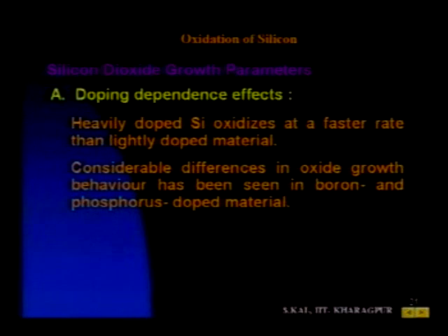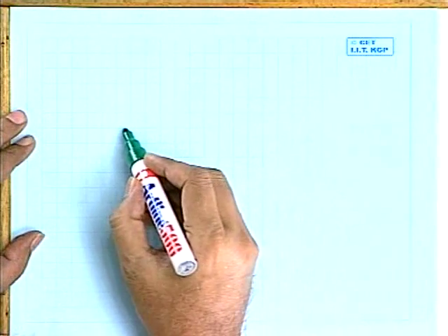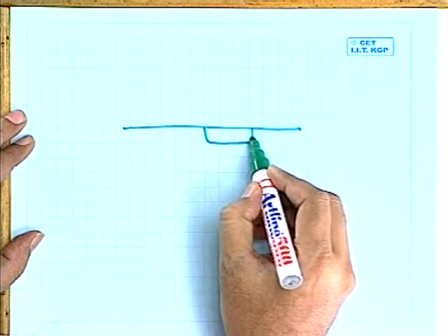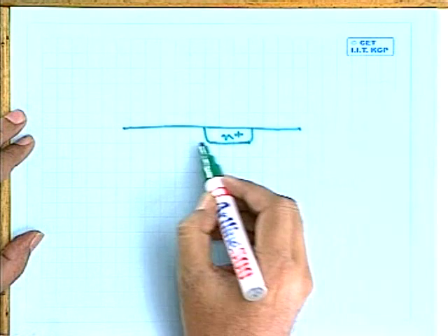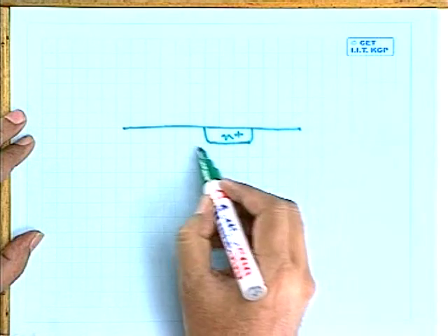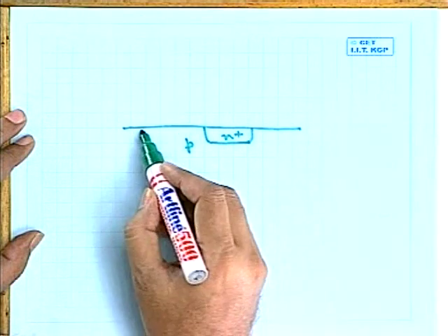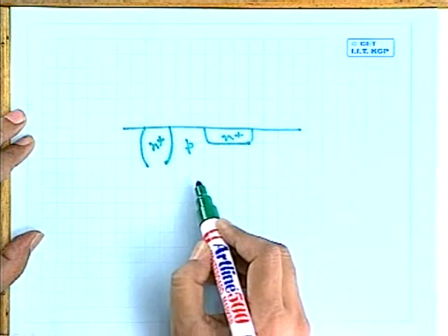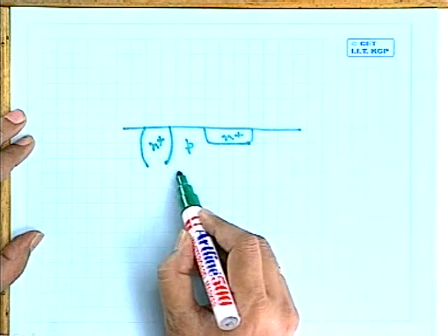So now at the surface, some regions are the emitter and some regions are the base and some regions are the collector. For example, if you look at a region like this, here on the surface, the emitter is N plus, then this is the base, which is P, and here is a deep collector. If you remember, the deep collector is N plus. So now here is a buried layer.